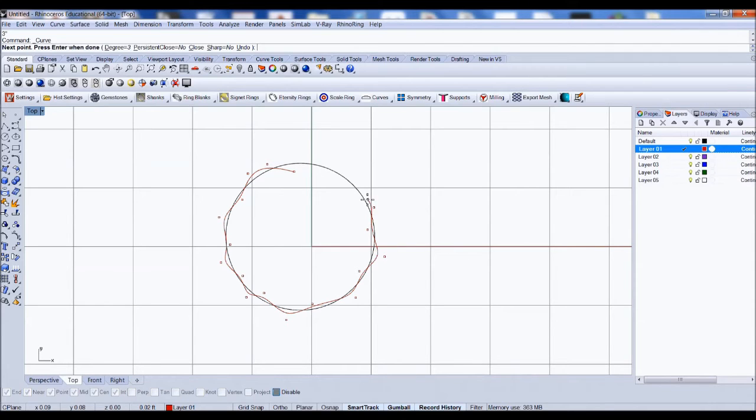And we are clicking along the curve, and these control points are what is creating our curve. And these control points are editable if you go to right here. It has the points on, points off. If you just left click with your mouse, you can turn these on, and you can just click that, and you can use a gumball to move them.